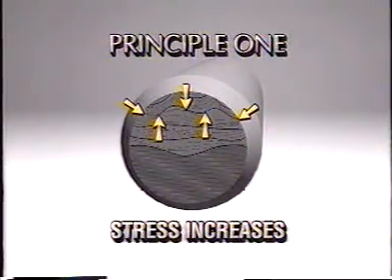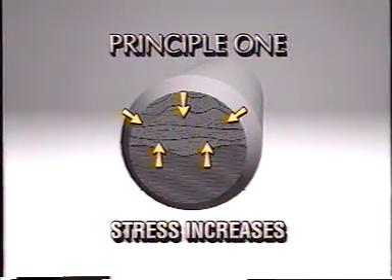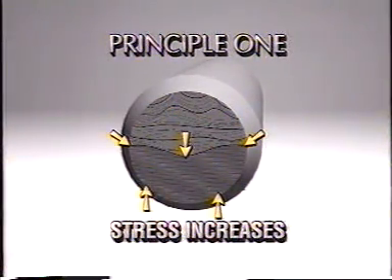Before the single crack front is formed, the individual microcracks will be separated by small vertical steps. These are the ratchet marks. At a stress just above the fatigue limit, the minimum stress for fracture, a single origin will occur. The entire fracture will emanate from this point.